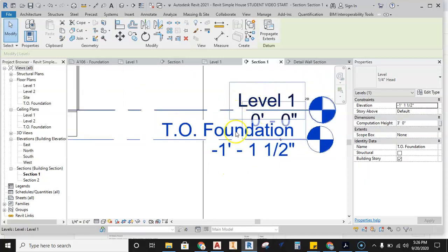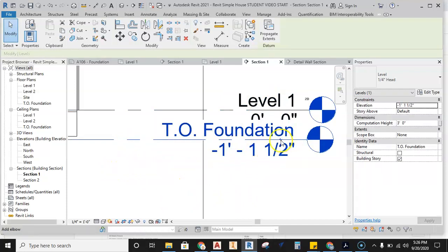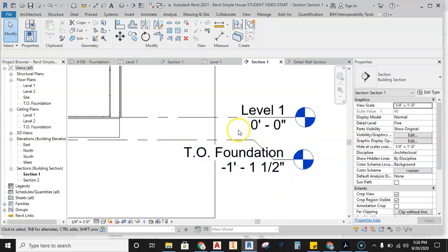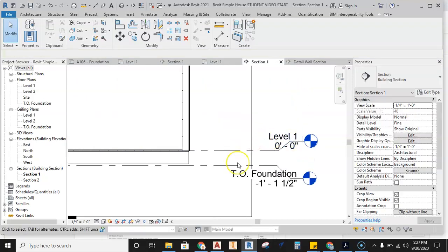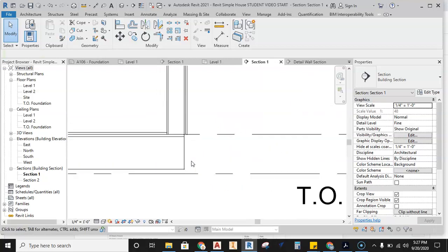Right away, what I want to do as it's in position is I want this not to overlap this, okay? So when you click on the line for a level, you see this little teeny tiny wiggly arrow here, this little zigzag right underneath of the name, between the name and the distance. Left click on it, and that adds an elbow, okay? Now, that allows you, if you needed to do two, it allows you to make one elbow go down and one elbow go up. That can keep things nice and neat and orderly. That's going to be critical later on when we start laying sheets out.